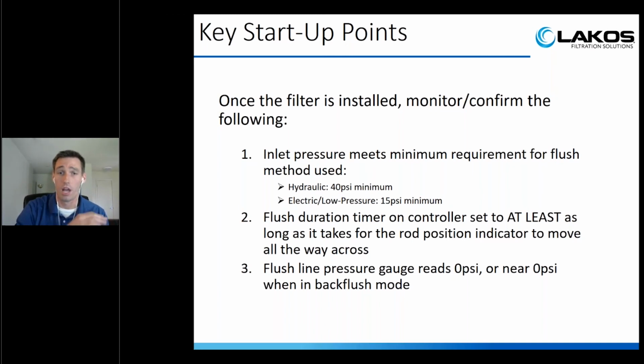If you have it set for a minute, all that's doing is the rod's not moving anymore. It's already pinged out all the way to the right. So it's going to be sitting there for 40 seconds, suctioning the same spot over and over and over. So all you're doing at that point is just wasting water. You're not actually doing more of a cleaning. So it's a fine tuning between making sure you clean the screen and don't waste water.